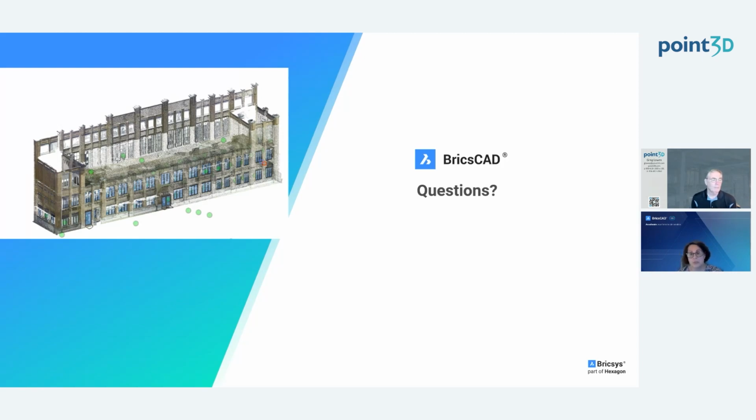BricsCAD itself does import quite a few different file formats: DXF, meta files, Collada files, DGN files. And then if you're really working more in the mechanical space, we have a product called BricsCAD Communicator, which allows you to import and export additional file formats, usually related around the mechanical space. So lots of different file formats that we do support.